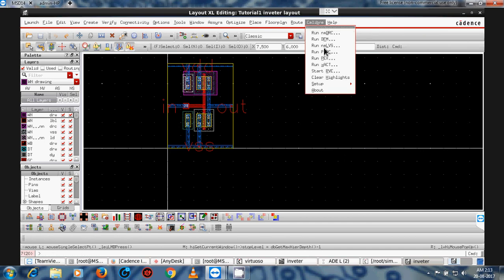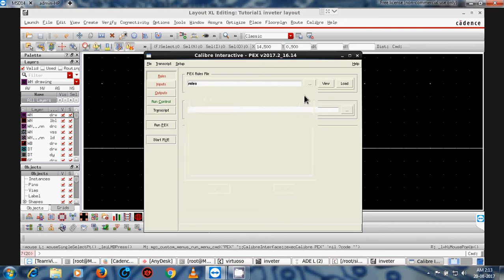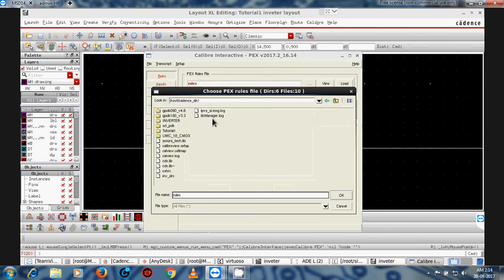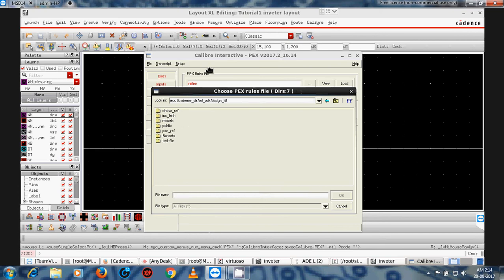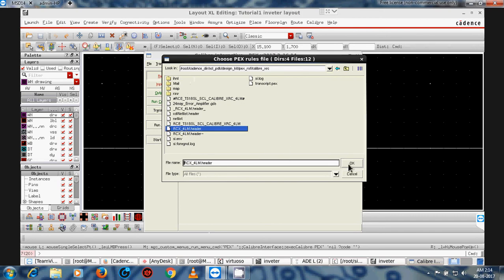Before post layout simulation, we again run these specs. Actually, here I am showing a tool, the Calibre tool, with a special property by which you can directly do post layout simulation. There is no need to create a testbench or anything else. But for this, you have to save your previous state. This is very important. If you have saved the state, then it will show the post layout simulation result.